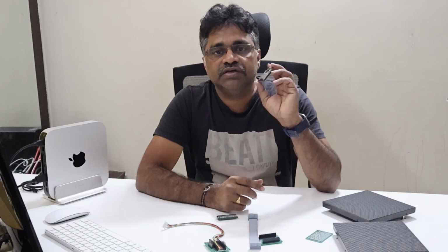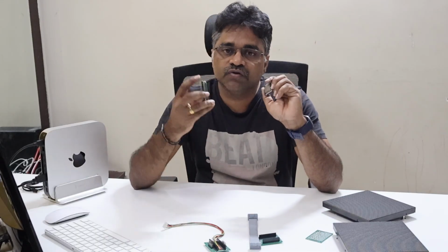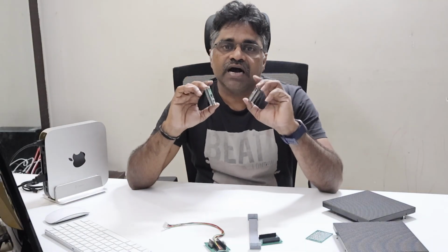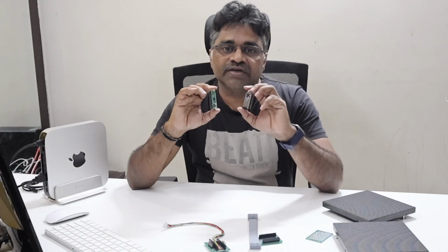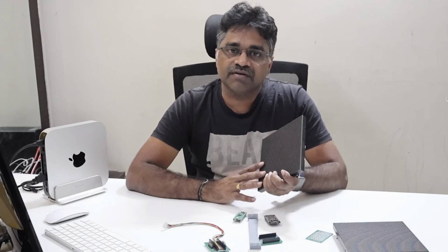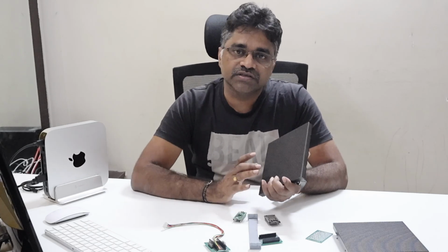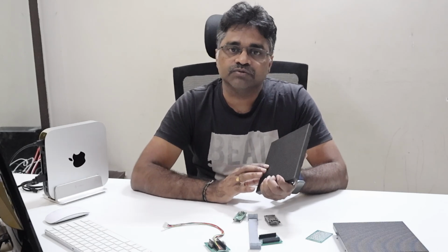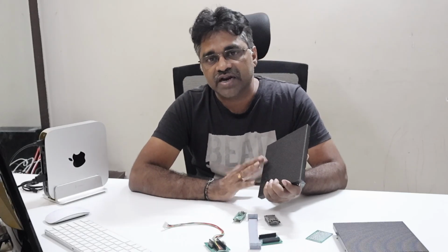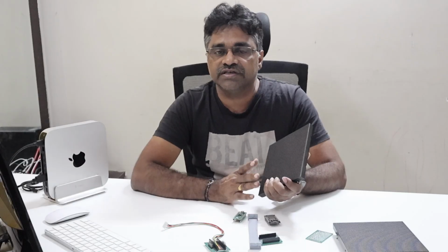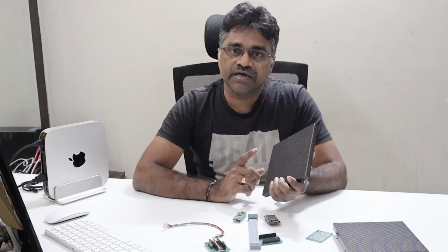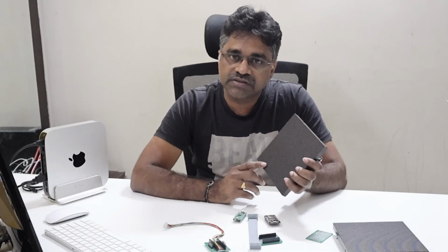When we use only the ESP32 or only the Raspberry Pi Pico to do all these tasks, running the application logic and driving the panel together, the panel refresh rate will drop. Then you will see some flicker or noise on the panel, and you don't see smooth text when you run animations like scrolling text, or transitions while changing the image, the frame or the page. You will see flickers, you don't see proper color, and you also see some noise.